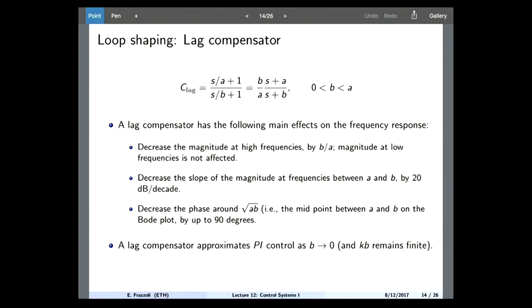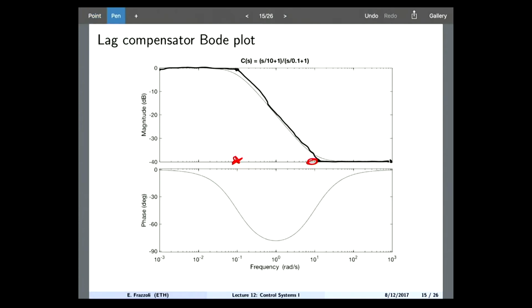The ratio of these two goes to 1, right? So then your gain at high frequency is B over A, right? So if I wanted to make this one, essentially what I'm doing is increasing the gain at low frequency by A over B. Okay, do you follow me?